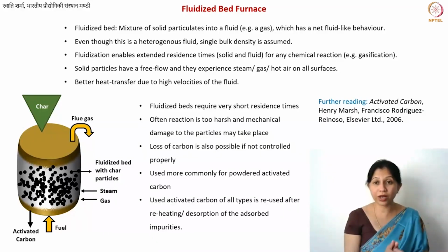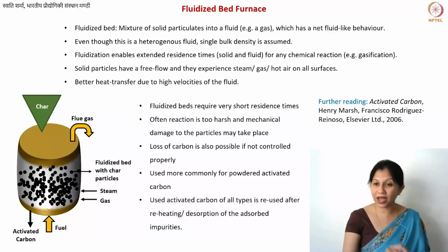Okay, if you want to read further on activated carbon, this is in itself a very vast field of research. This is one book that I suggest. There are also several papers and review articles that you can read. Activated carbon is also very important for waste treatment. If you carbonize waste polymers, often you end up getting either a mixed type of carbon, or you get porous carbon. You don't get good quality graphite or glass-like carbon, of course, from the waste. So in that case, conversion of char into activated carbon, and then utilizing these activated carbons for different processes, is very important.